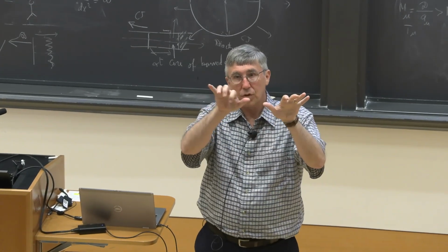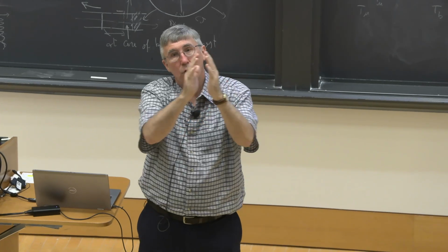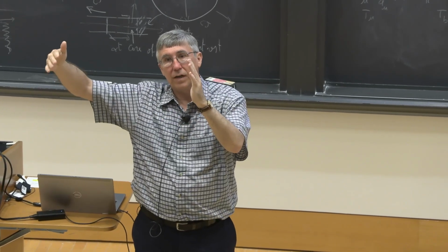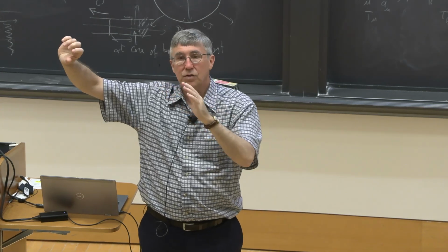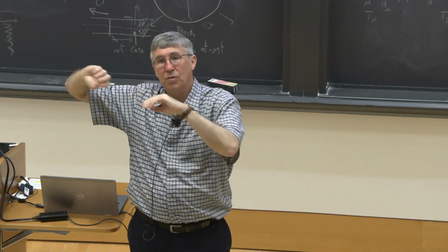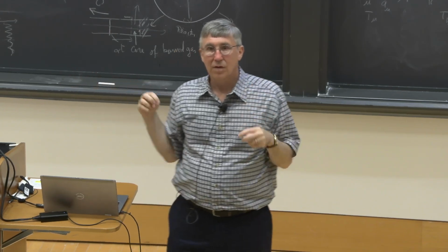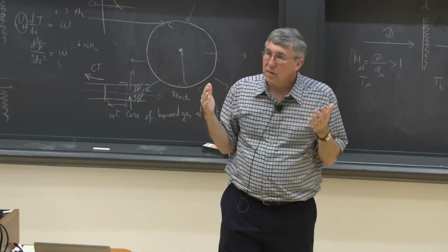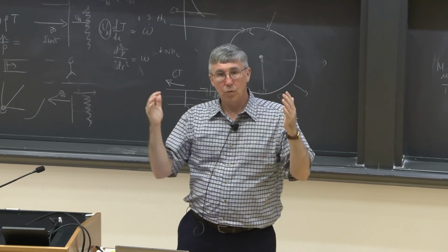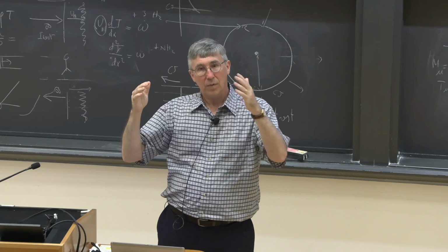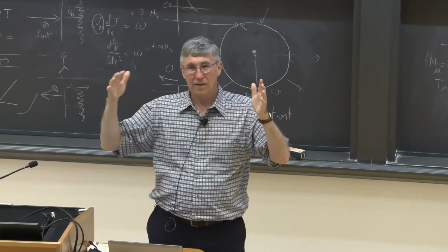At the contact surface where the two of them are touching, there'll be a little bit of mixing, but typically that's moving so slowly that it doesn't get to the region you're looking at for the experiment, which is all the way down at the end, until a long time scale. So when that finally gets close to you, typically you're done with your experiment. You hope that all the radicals have reacted away. But that also means you have a limited time scale that you can operate with the shock tube before it's all going to be messed up from the contact surface moving, from the reflected rarefaction waves, and a lot of other effects.